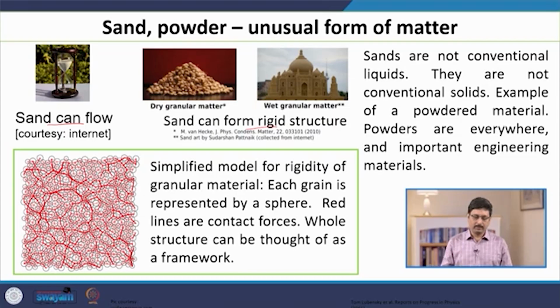Now, I must mention one more thing, that sands or powders are not conventional liquids like water, because their flow properties are very different from a typical liquid like water. They are also not a conventional solid, in the sense that it remains a solid body only when you compress them enough so that they achieve a high enough density, and you have to hold them in a rigid form by external force.